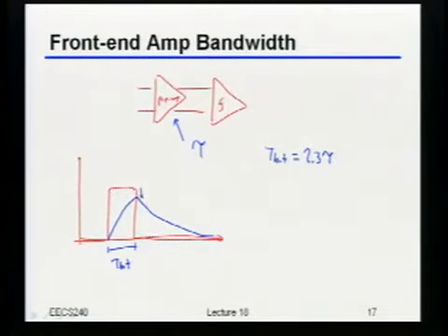What would be the residual error I'd get right there? How far from the transmitted voltage would the output of my receiver get? Assuming a gain of 1, of course, or in a normalized way. 10%. Yeah, it's 10%. Remember, it's that 2.3 tau per decade. That means I'd get to within 10% of the final value. Okay?